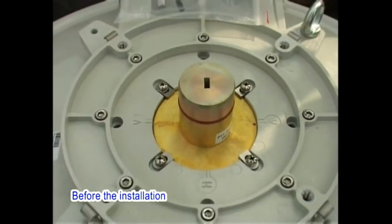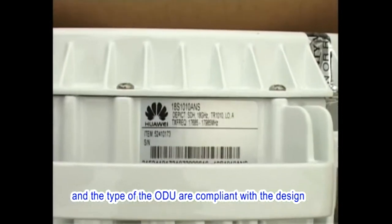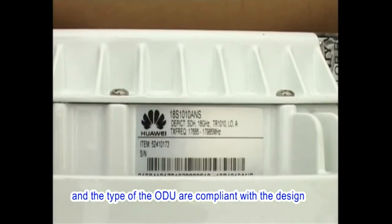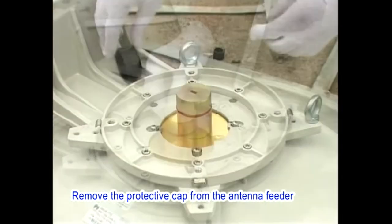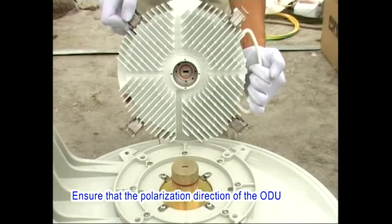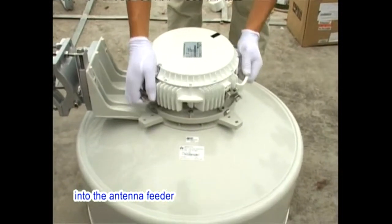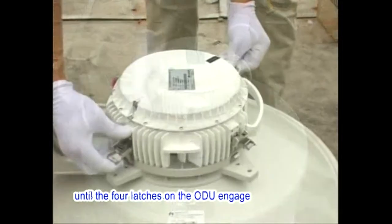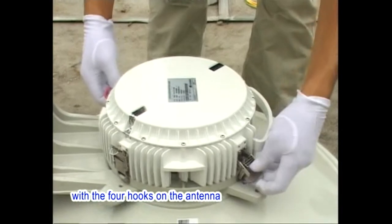Before the installation, ensure that the polarization direction of the antenna and the type of the ODU are compliant with the design. Remove the protective cap from the antenna feeder. Apply appropriate lubricant to the gasket of the feeder. Ensure that the polarization direction of the ODU is the same as that of the antenna. Slowly feed the antenna interface of the ODU into the antenna feeder until the 4 latches on the ODU engage with the 4 hooks on the antenna.